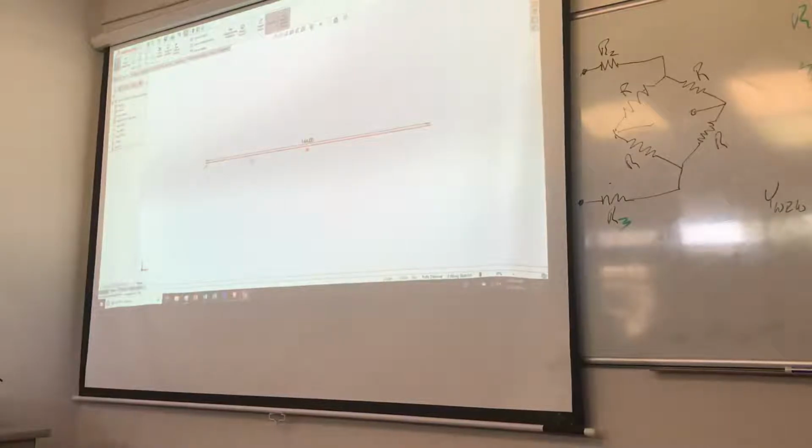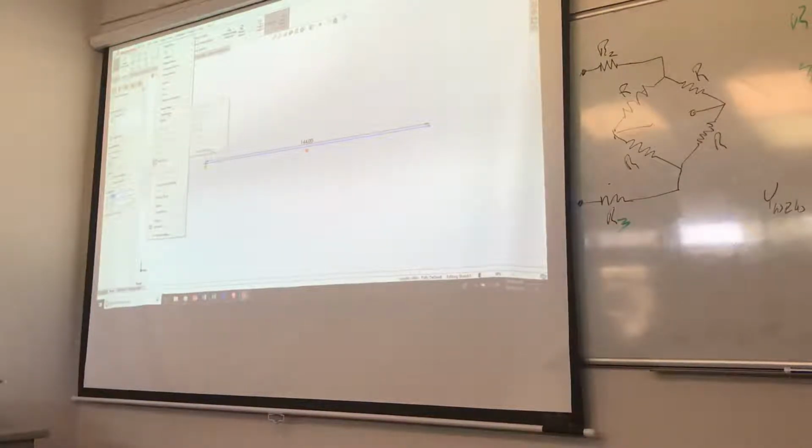that's how we do that, is we select the line, or the one we want to do, and we go to Insert, Weldments. Okay. I got to get out of the sketch. That always is my shortcoming. Insert Weldments, and it gives me a choice of a weldment or a structural member, and we want to do a structural member.